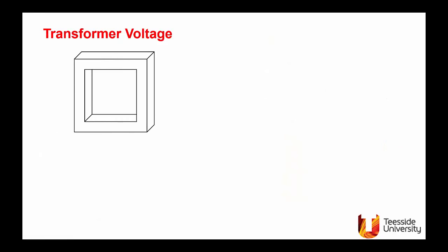First, we consider the case when the voltage is induced in a coil that is excited by a current. So we have a magnetic core here, and around it a coil, the blue coil, carrying current I. The flux lines, if you apply the right-hand rule, will be like shown in red. Now, I assume that the current is sinusoidal, i.e. it's I maximum sine omega t.